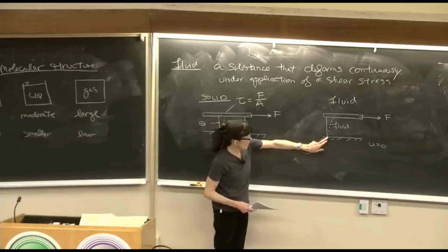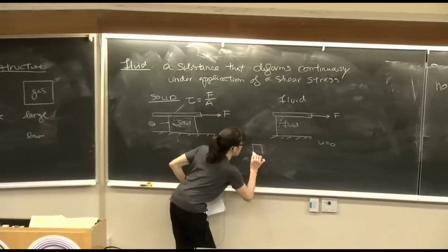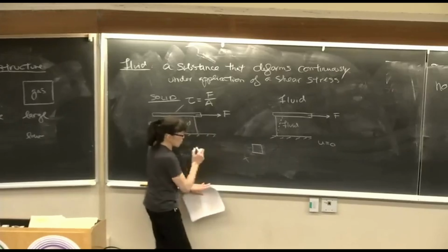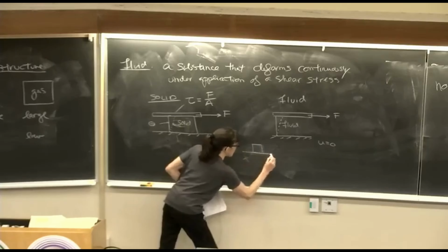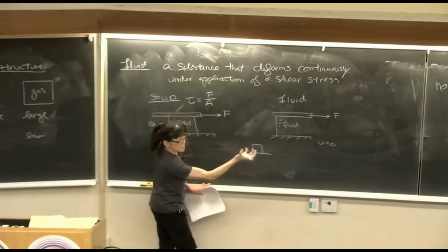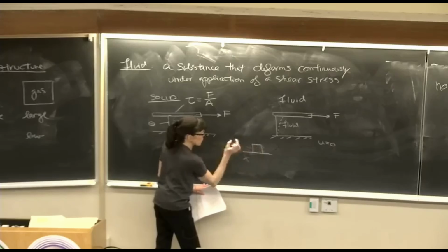Maybe I can consider a small infinitesimal cubicle fluid particle. Because of this stickiness of viscosity, it's going to stick to the lower surface. And so this infinitesimal fluid particle is stuck to the wall, so it will take on the velocity of the wall,